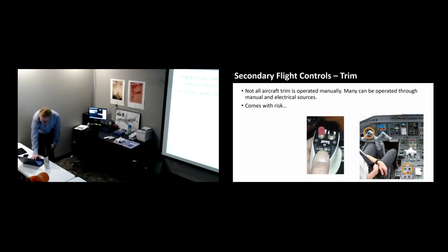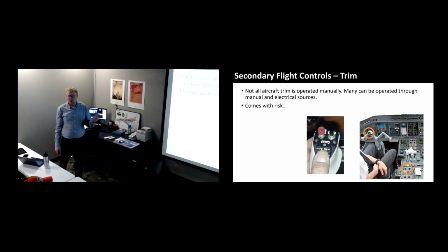But if you go after this, I'll show you guys. So you go down to 172. This switch is split, as there are two switches, a left half and a right half. You have to move both of them to actually get the trim to actuate, and it does require a good bit of force to move. So it's not like a light pressure input will do that.